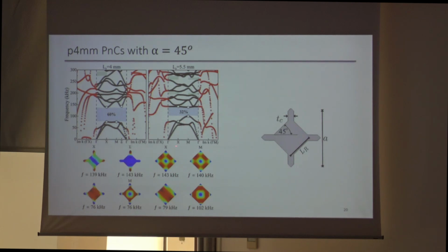And this happens because the connectors become very narrow, and when they are very narrow, it's more difficult for the resonator to resonate, and also its frequency increases, and that's why we have shrinking of the band gap. And here also, if we look at the imaginary part, we will see the strong coupling of the resonance and Bragg band gap, because the imaginary K is very, very far.